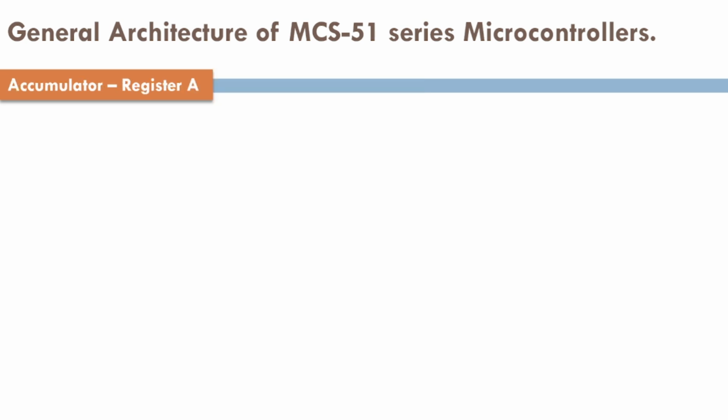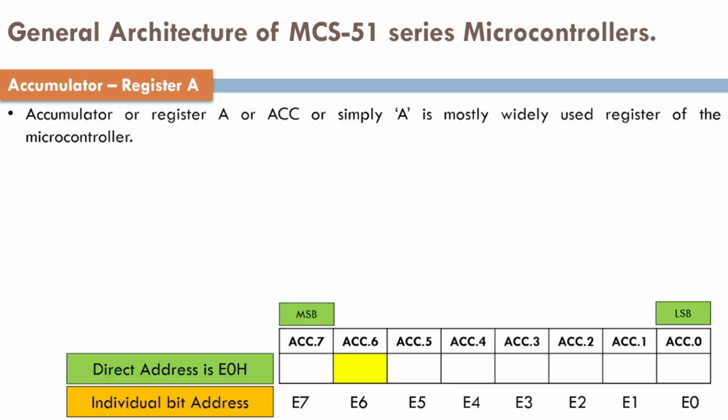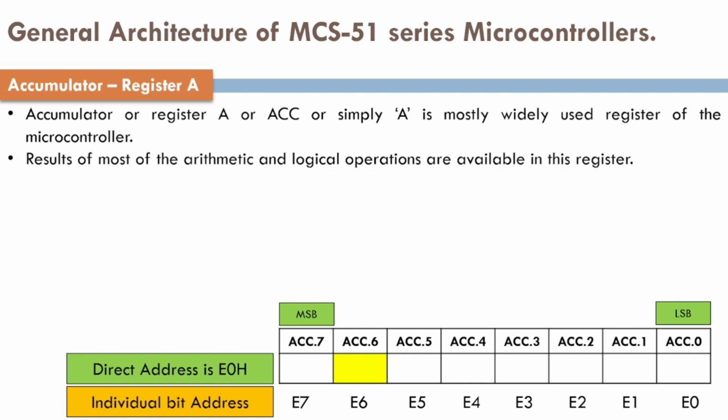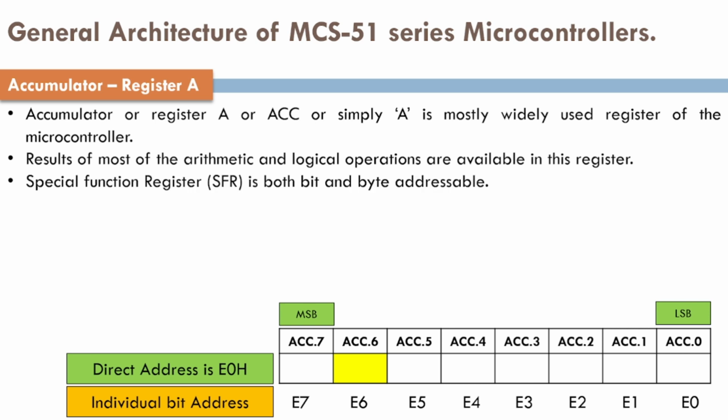Accumulator, or register A, or ACC, or simply A, is the most widely used register of the microcontroller. Results of most of the arithmetic and logical operations are available in this register. It is also a special function register, SFR, and it is both bit and byte addressable.